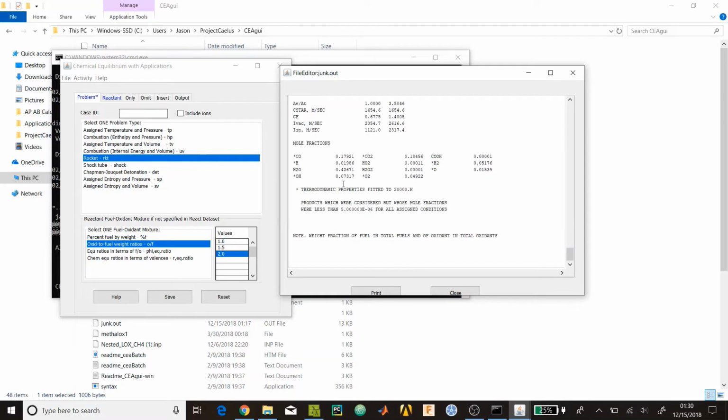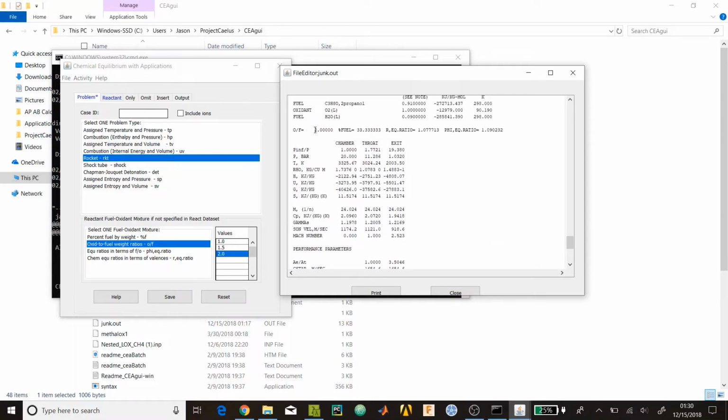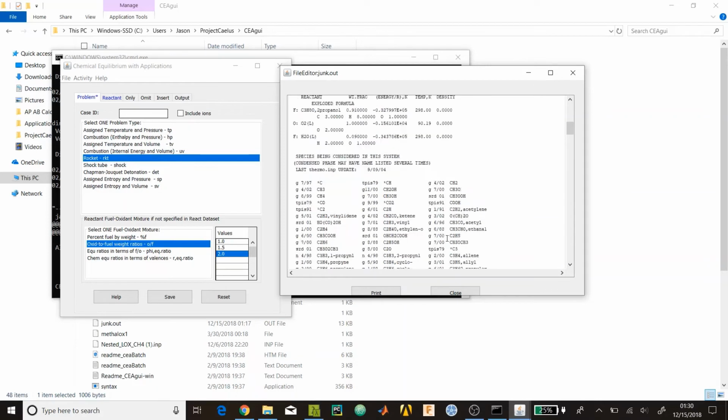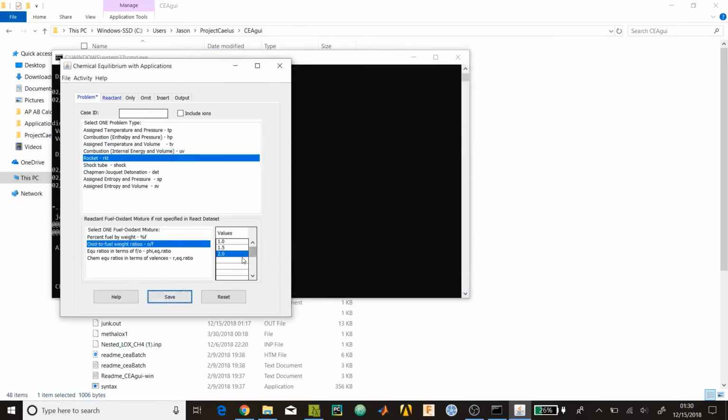2. Alright, well at 2 we have even higher and even higher. So we're seeing that it's still getting higher as we're increasing our oxidizer fuel ratio. So what you can actually do is come back and say, okay, we know that 2.0 was good, but we can try going higher. Or in fact, you might want to try 1.7 because you don't know which way it got better. You don't know if the maximum is between 1.5 and 2 or if it's higher than 2.